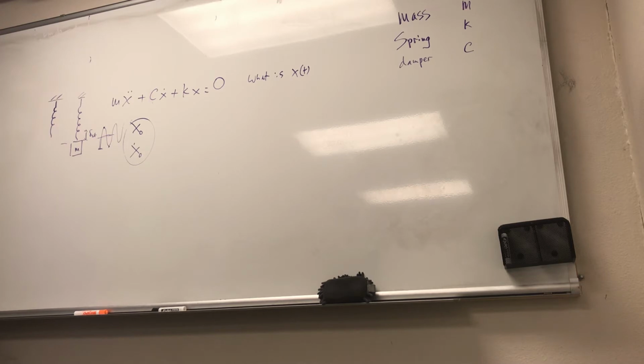Only one. I could maybe use x or theta. But I can't say x and theta because x is redundant, exactly. Because if the length of this arm is L, x is equal to L times the sine of theta. So they are dependent, okay? So this is, again, a 1 degree of freedom system. That's only one piece of information that you need.